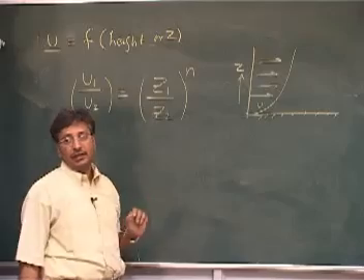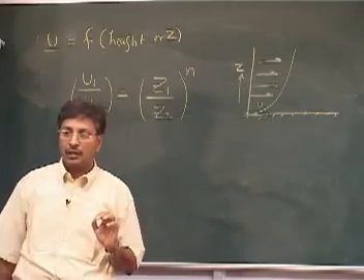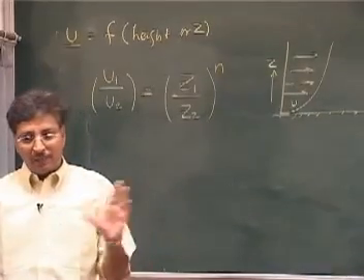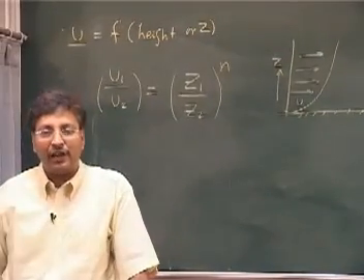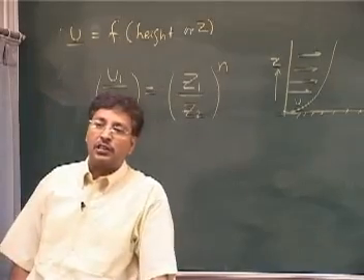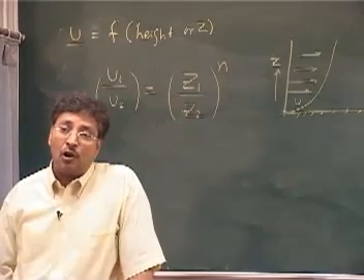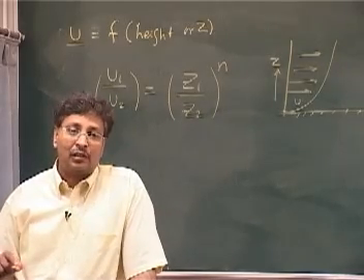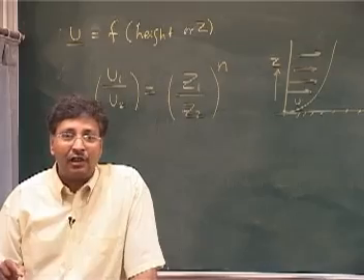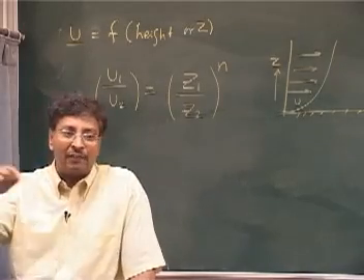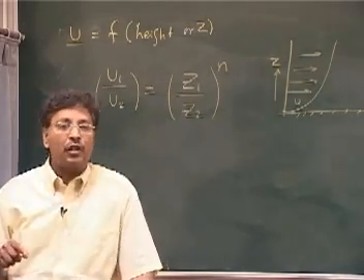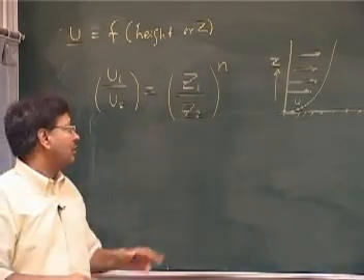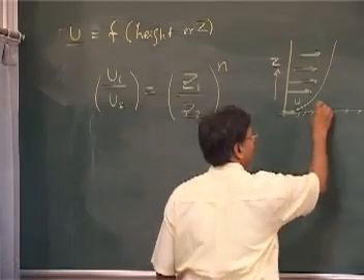This parameter n depends on two things. Stability, because stability can disturb your wind profile, right? And also the conditions, whether these are urban conditions or rural conditions. So the wind profile, if you go to the Connaught Place area of Delhi, it will become very different, because of the buildings, the roughness and things like that. And if you go to an area like the Gangetic Plain, flat terrain, things will be different.